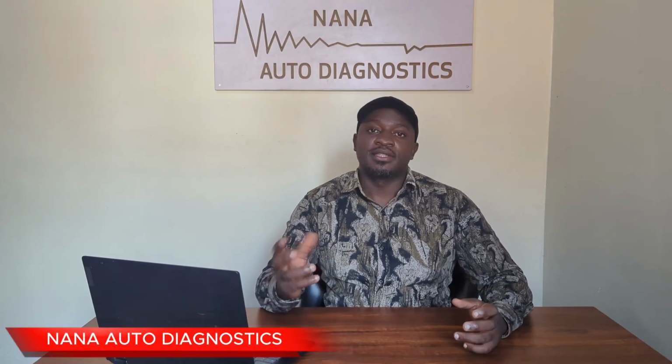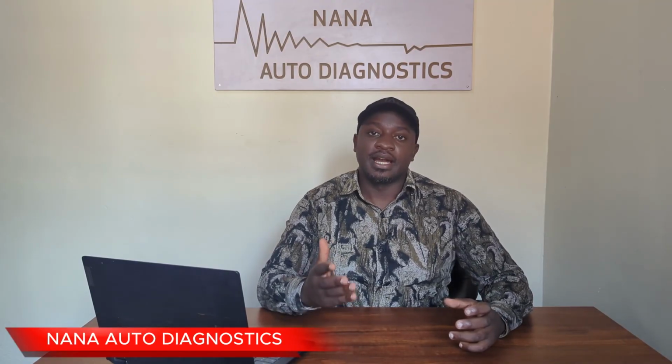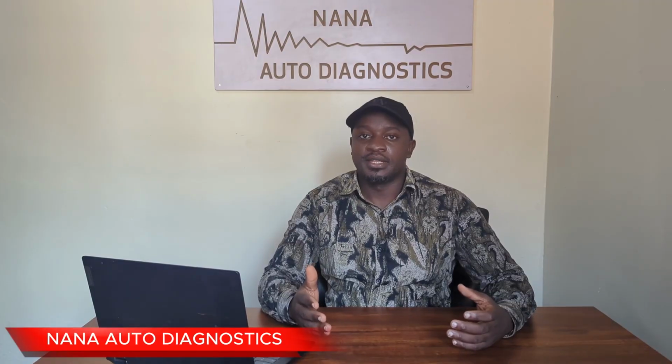So we cannot access this network on the DLC or the OBD2 port. It's only the J1850, the K-line and the CAN which can be used for scan tool to module communication. LIN is only used for module-to-module communication.